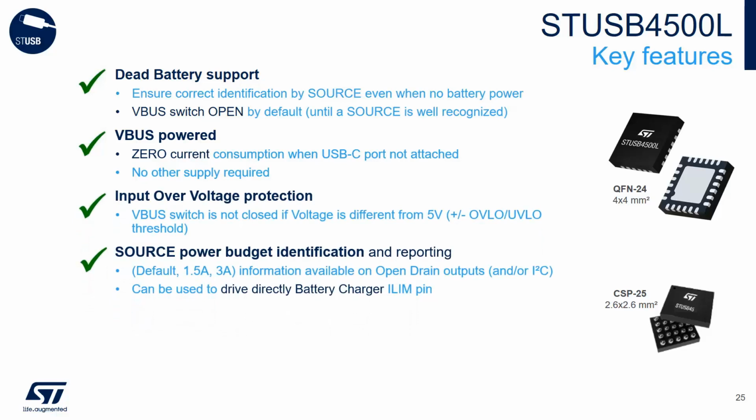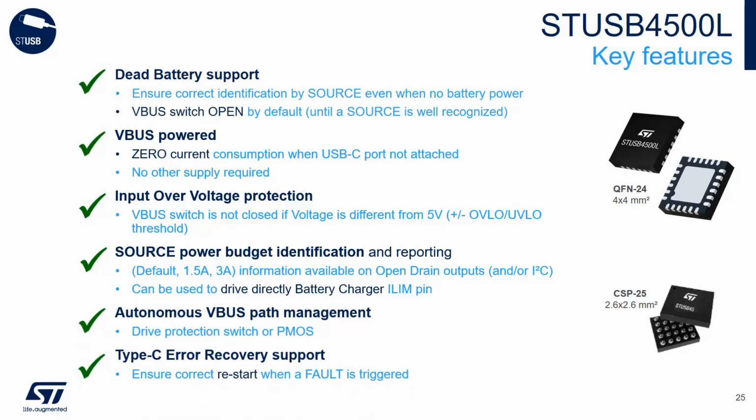It performs under and over voltage protection, of course, and it implements automatic power budget reporting, which is the duty of the sync device, in order to set the maximum charging current. And especially important, it implements error recovery in order to restart from a fault condition.